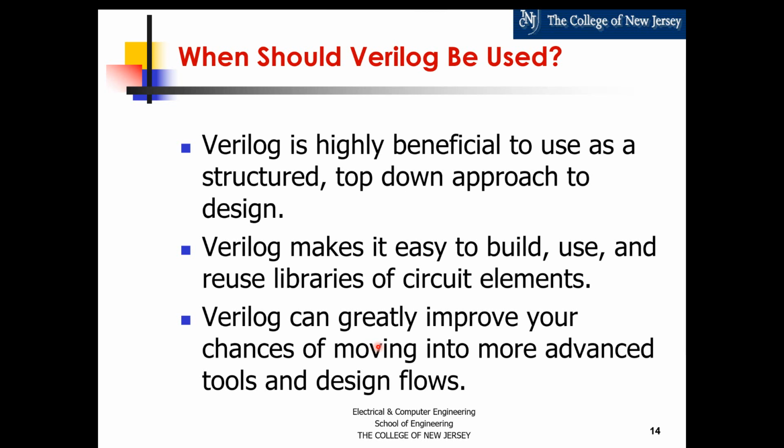What you will find is that you can use different design approaches with the hardware description language. You can do top-down design, where you start describing the functionality from the top of the functional hierarchy, assuming that you have the lower levels, and keep traversing that hierarchy down until you get to the leaf type of functions.